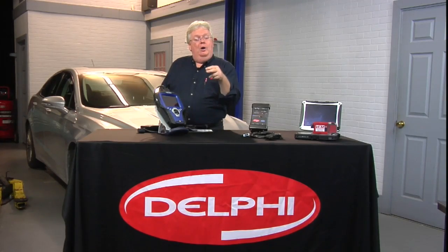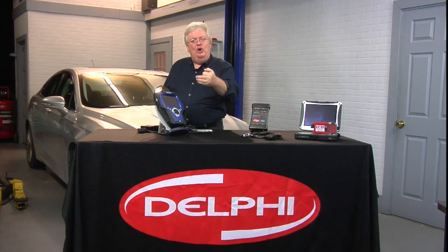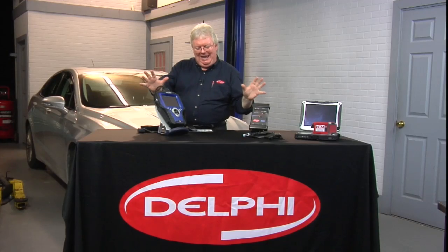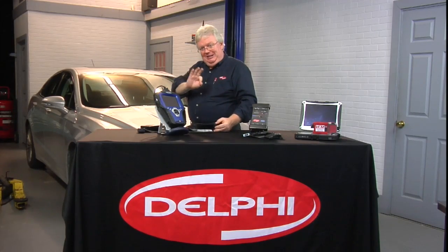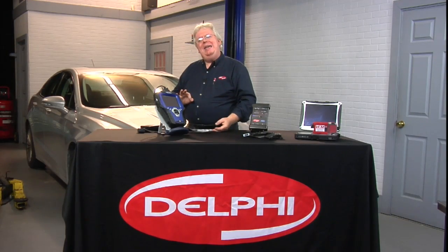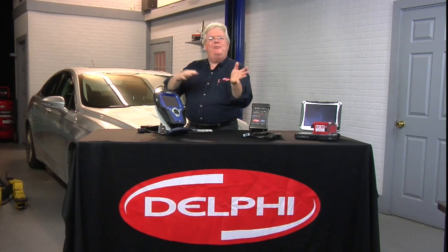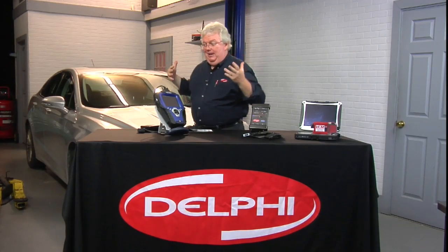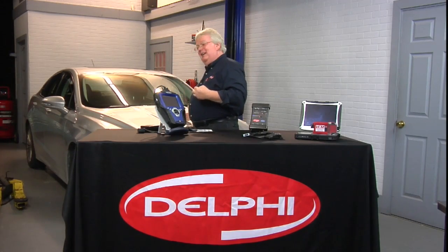Normally in the old days we'd see -40. If it was shorted, we'd see 300 or something like that. On enhanced OBD II live data, like we usually do with our scanners, you'll see today, more than ever, a made up number, and it's believable. It's not a zero, it's not exactly at some spec like -40 or 300, the very edge. It says 150, and by golly, my intake air temperature says about that too.